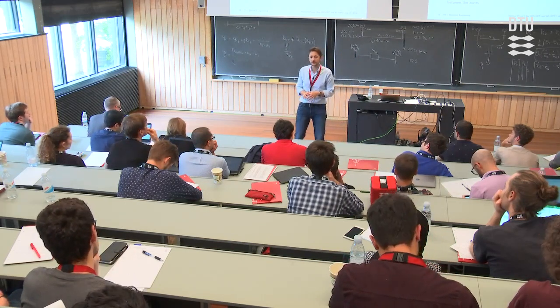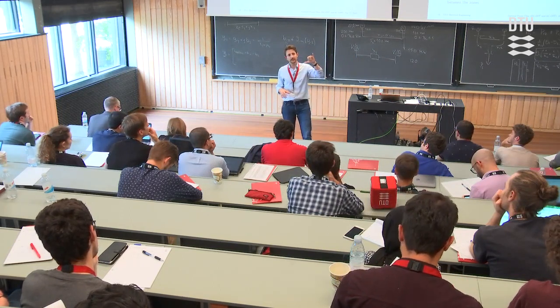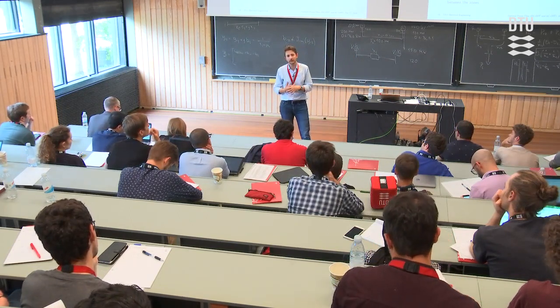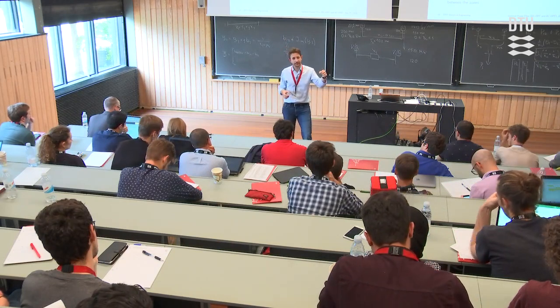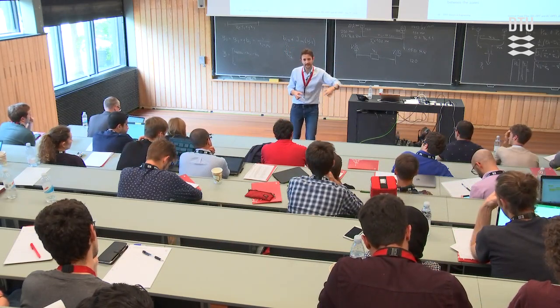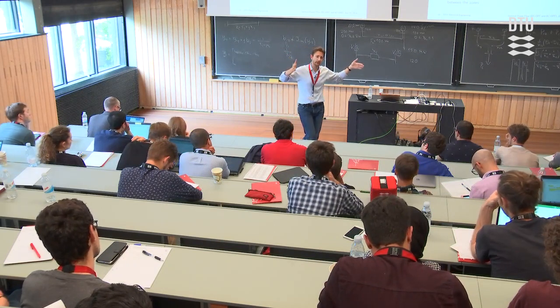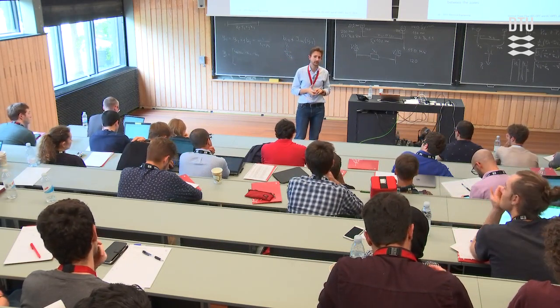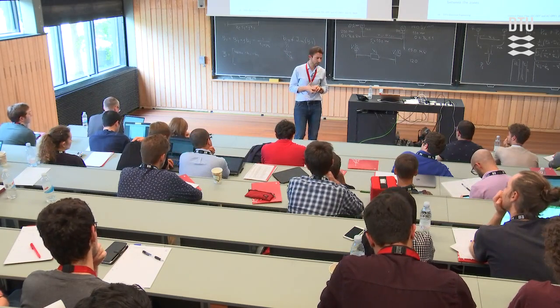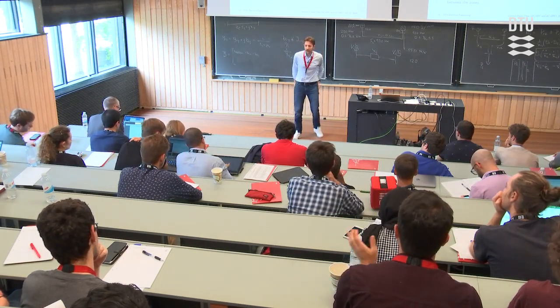Okay. But putting a limit on the angles, in the DC-OPF, you usually don't do it. In the AC OPF, you do it because every 360 degrees, you have exactly the same voltage, right? So you put a limit so the optimization can look into 0 to 360. Clear? Yeah. Okay. Other questions?